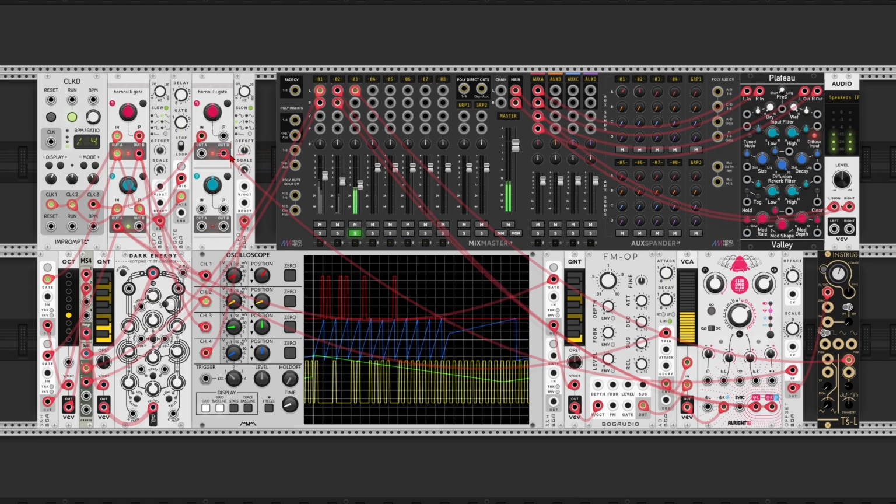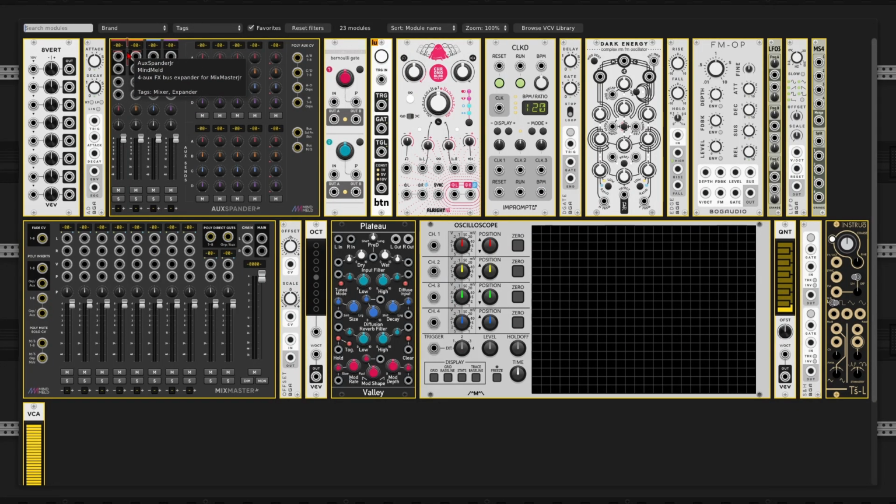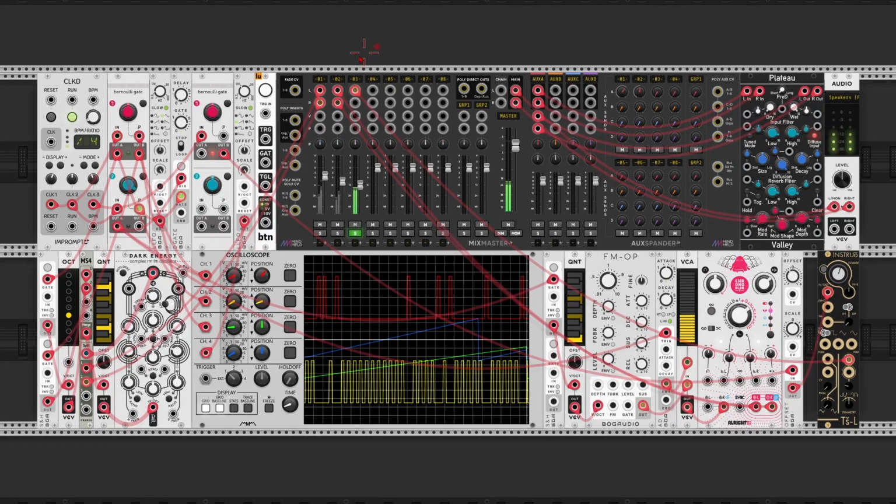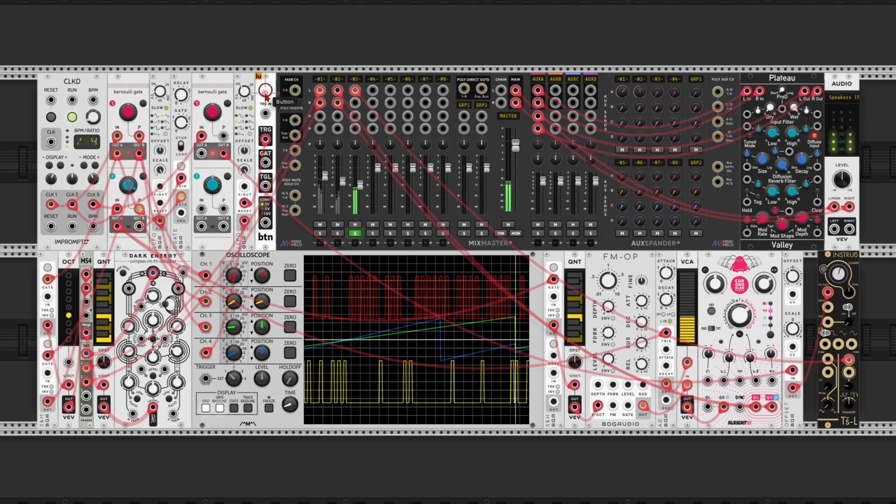And now we need a way to make a change in the B output move the LFO to that -5 volts position. I'll temporarily add a button module from little Utils to simulate that B output change. Hook up the trigger output to the reset input of the LFO. And now each time I click on the button, you'll see that the LFO output jumps back to that -5 volt position, because that's where it resets to. So sending a trigger on that reset input is exactly what we need to bring our probability down to 0.